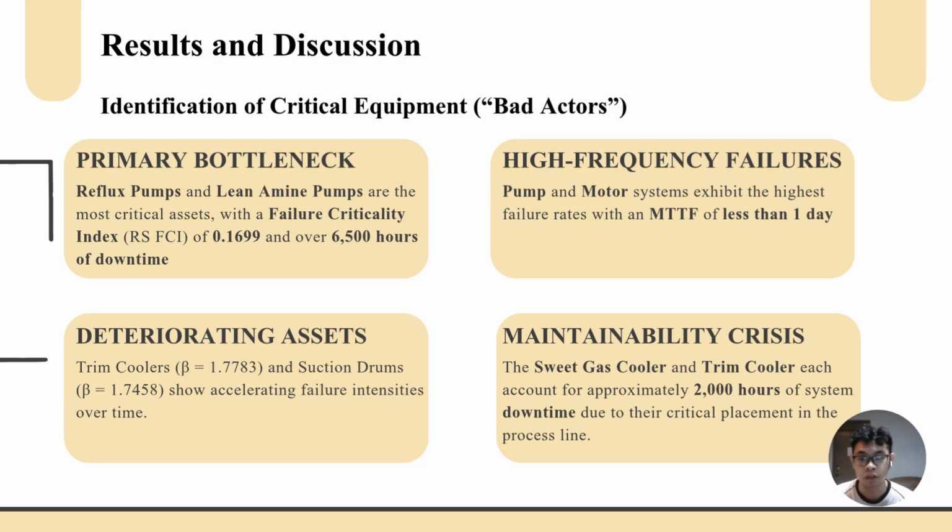This high frequency is compounded by deteriorating reliability trends. Specifically, our repairable data analysis, RDA, results show that the trim coolers and the suction drums are rapidly deteriorating, with beta values of 1.77 and 1.75 respectively. And this means that the failure intensity is actually accelerating as the plant ages.